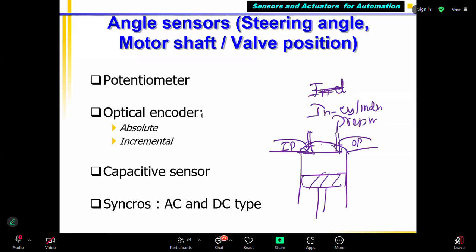Then you want to measure this in-cylinder pressure. How will the in-cylinder pressure vary? It varies like this generally. For the four-stroke engine, the x-axis is 0 to 720 degrees crank angle. We say crankshaft angle or crank angle. And the pressure increases something like this.